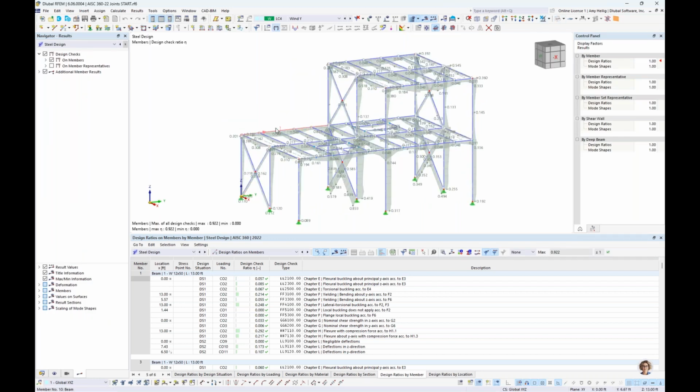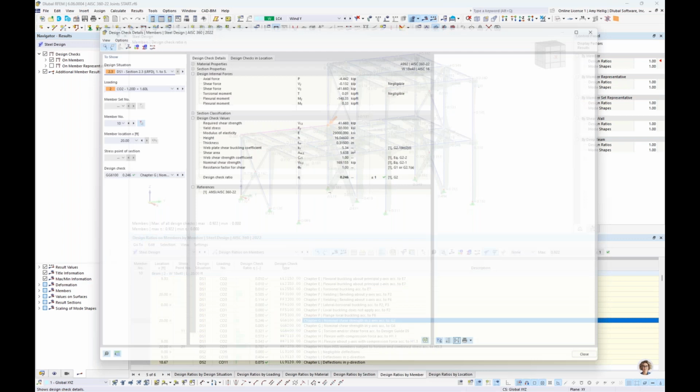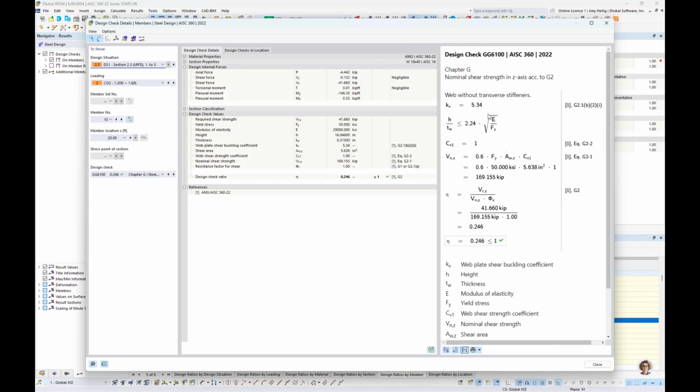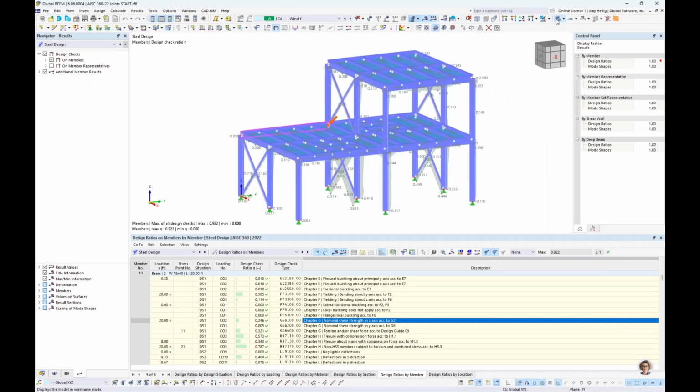And if I click on this back girder, you'll notice that all of our design checks from the AISC 360 are listed here. For each one of these, we further have the ability to take a look at the design check details. So this is going to show us line by line these various formulas, along with the code references and the relevant design ratio that we're going to get for the member design. So once we feel comfortable here with the member design, what we would like to do is the connection.